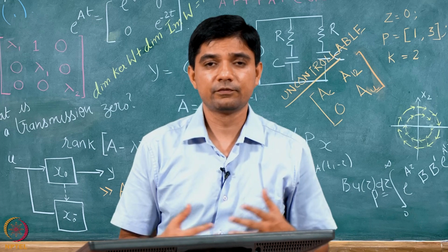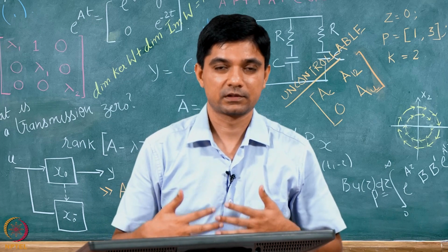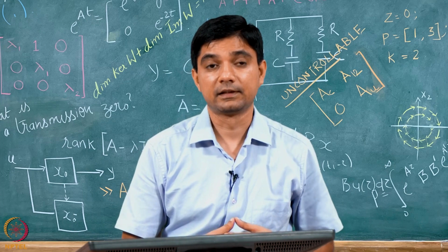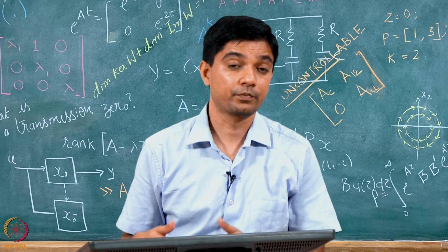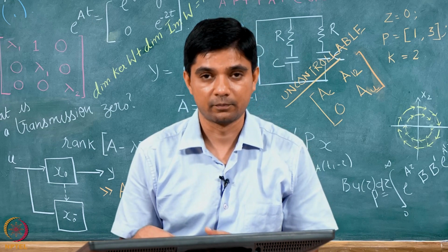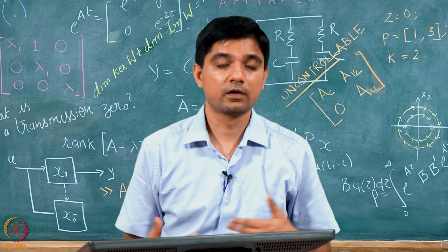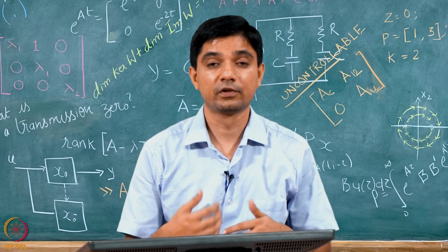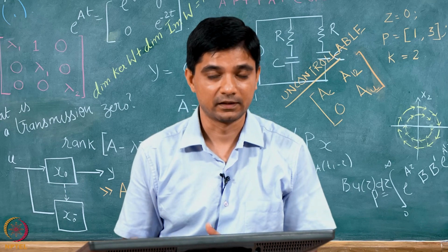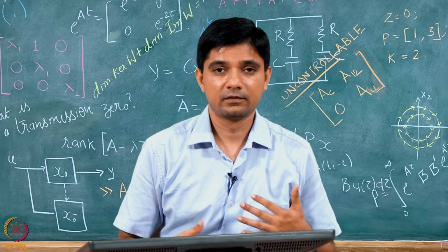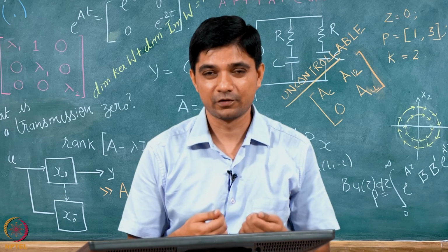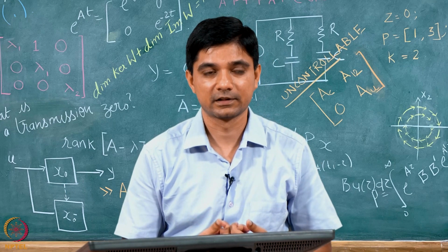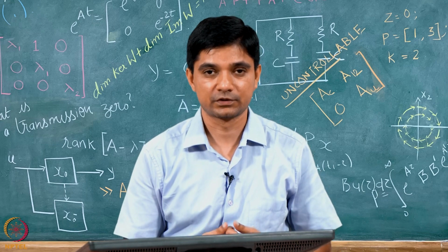A bunch of things we derived today, starting from the definition of controllability and then to do with some eigenvalue and eigenvector properties of A transpose and B transpose. We also found a beautiful relation between controllability and Lyapunov stability. These are details which it may help for you to work out by yourself, and check those proofs again.